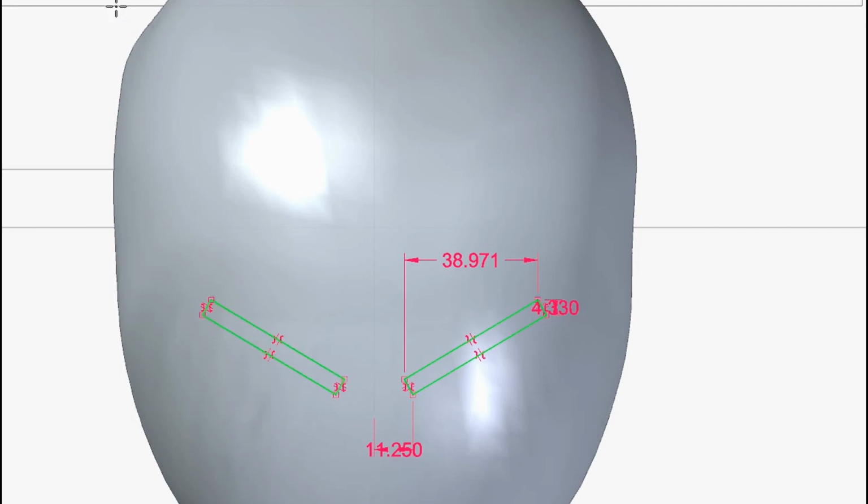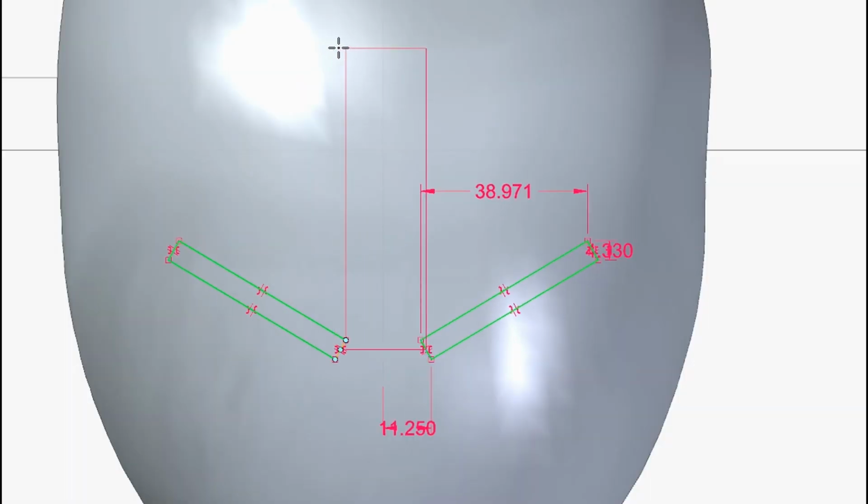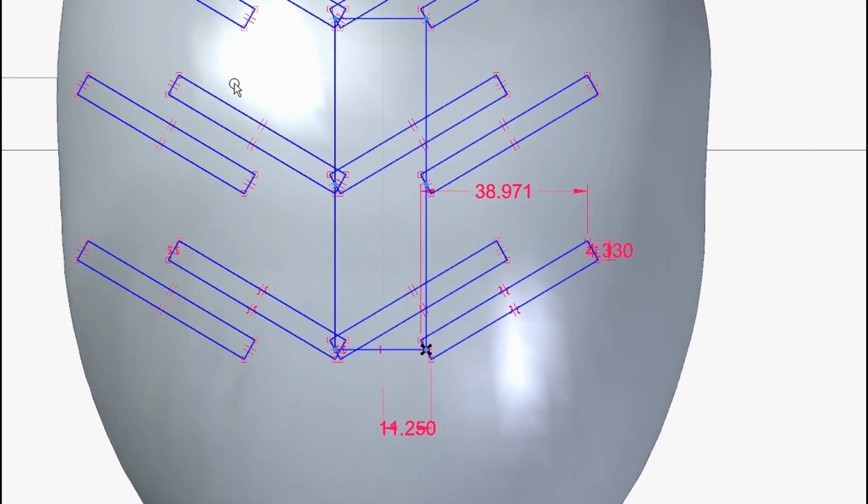You'll select your sketch elements that you want to pattern. And then you go ahead and create your rectangle from the starting point of the pattern. And then you choose how many instances you want in the X and Y direction. And of course, you can also control the dimensions of the rectangle, and you're pretty much done. And you can click on that rectangle again to modify the pattern parameters there.